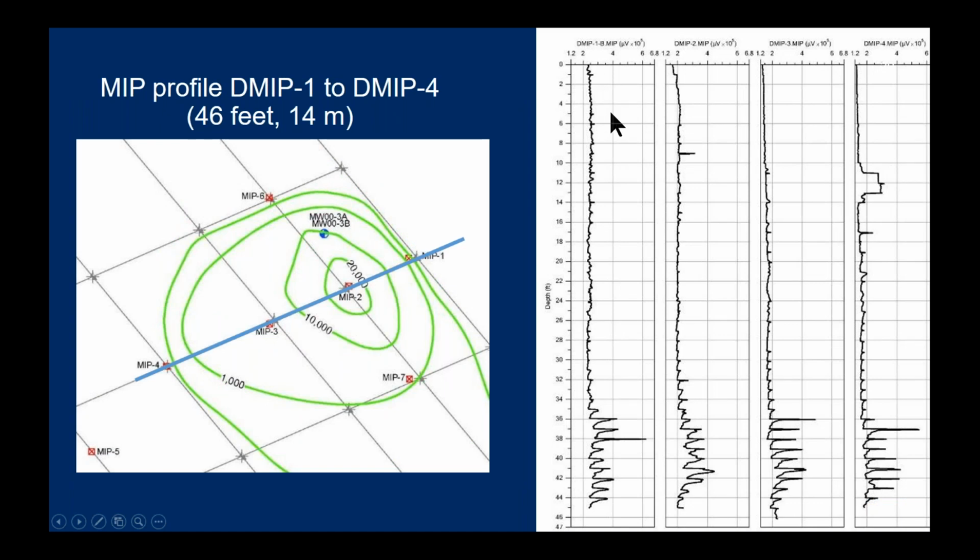And most of the depth of the aquifer, so down to about 36 feet below grade, we didn't see much signal from the MIP borings. You can see it's all fairly low. And then the impacts start right near the interface between the aquifer and the aquitard, which makes some sense with the contaminant that we're dealing with, mainly TCE.